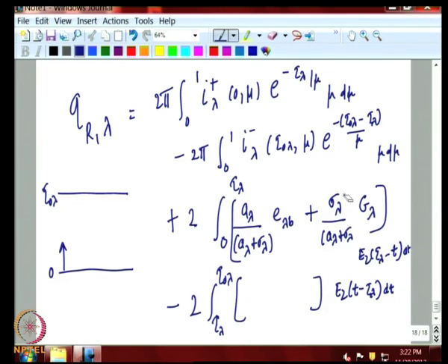So, you have to solve for both, and so the problem gets an order of magnitude more complex, because the way you treat angular variation now is much more critical than what it was in the case where there was no scattering. So, basically the pure absorption emission problems were much simpler to deal with compared to what we now deal with when we look at combined absorption and scattering.